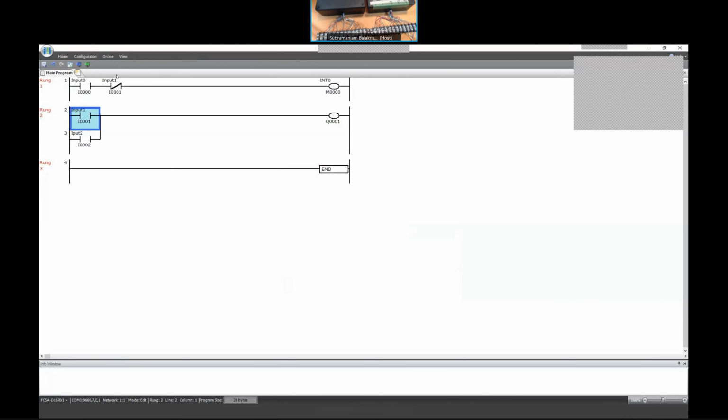So abbreviate. So I changed this to not a hard output, but an internal relay, which is a software register inside the PLC. The difference between the internal and an external output: the internal sets a flag inside the PLC, which can be used as a variable again elsewhere in the program.